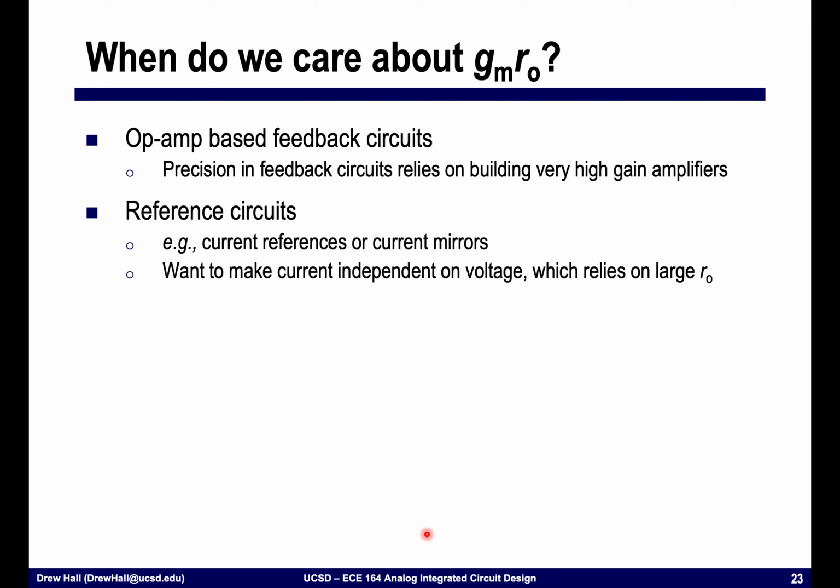We want to make currents that are independent of voltage, and this relies on us having very large output impedance. And there will be a few other examples where we'll talk about the importance of intrinsic gain later on.